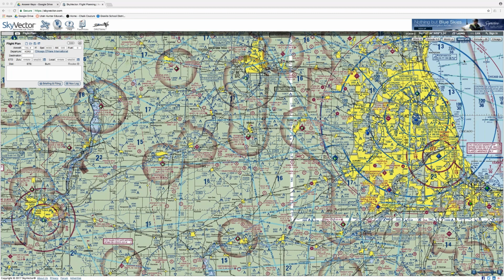Do you know the 1, 2, 3 rule? Okay, go ahead and give it to me, CJ. You don't have to list an alternate for at least 1 hour before and 1 hour after your time of arrival, and then your ceilings at least 2,000 feet, and you have 3 miles of visibility.